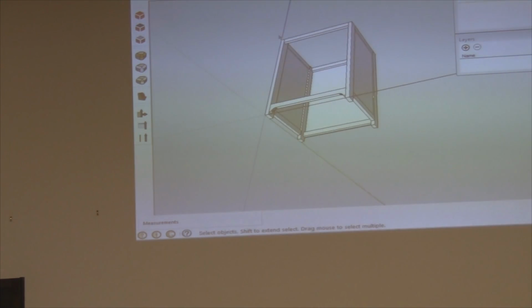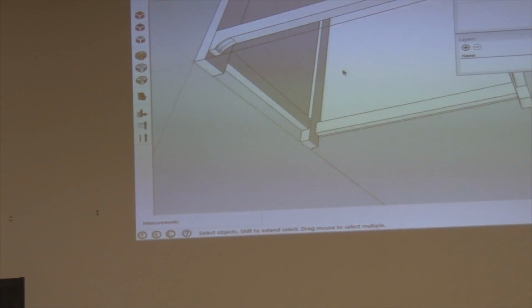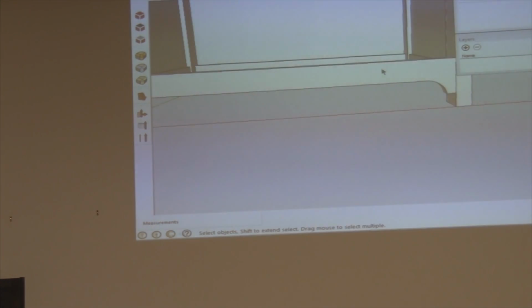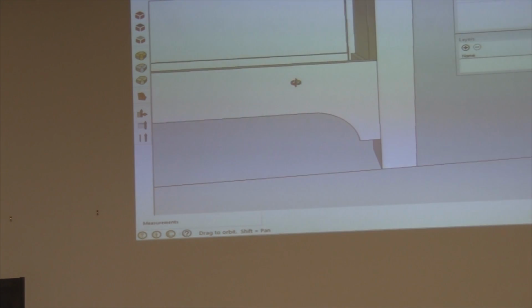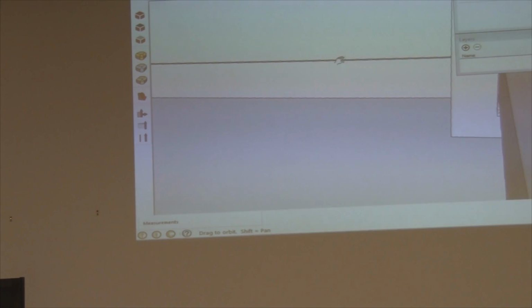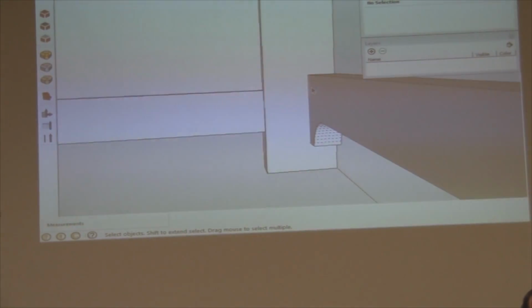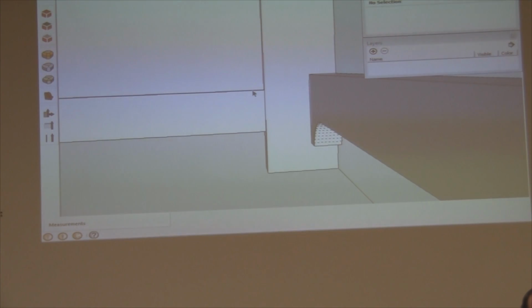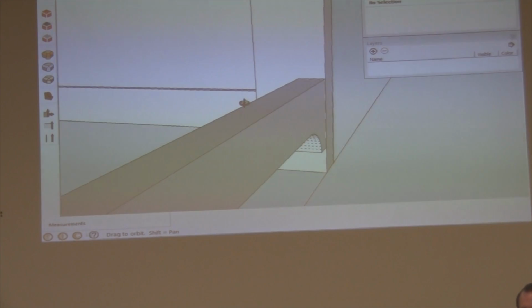Now we are ready to basically put some supports in for the bottom shelf. So we actually want to put just a plywood bottom in here, and we want it to sit in here nice and flush. If you take a look at it from this angle, this front actually sits 1/2 inch proud of this piece right here. You see that? So our shelf, we want it to sit flush with this, and then the top of it is going to be flush with the front. That way we don't see the edge, it comes out nice and clean.